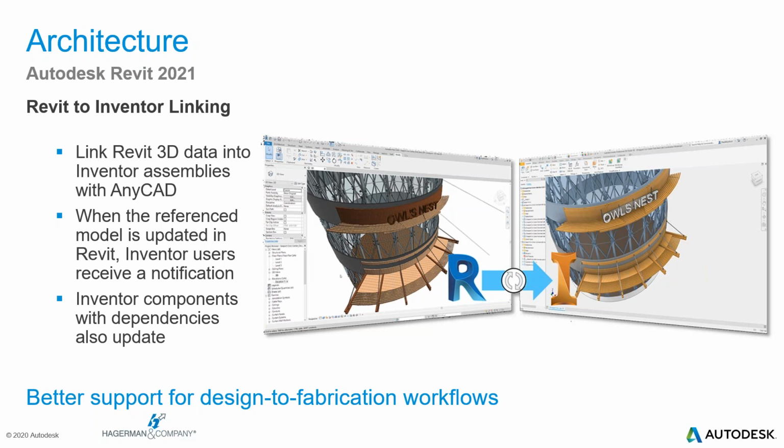In Revit 2021, you can define such 3D rebar shapes by rotating the hooks at the ends of the bars and directly inputting the hook lengths for each rebar instance. Hook rotation is considered when defining a rebar shape if included in the rebar shape definition. Rebar numbering considers hook rotation along with the other segment length parameters. You can also change hook lengths quickly for each bar in the project.